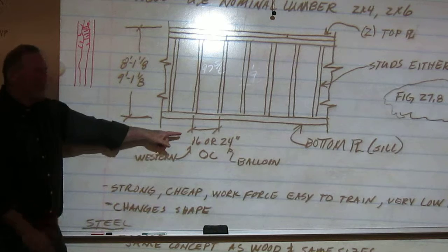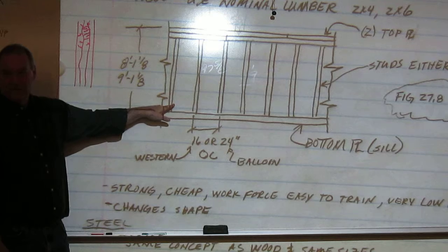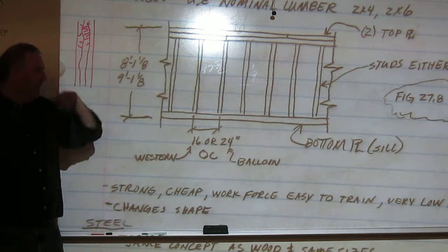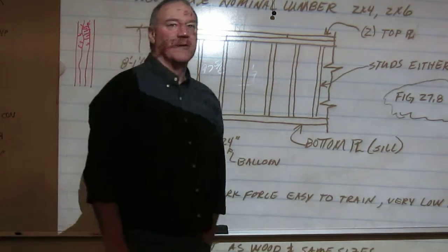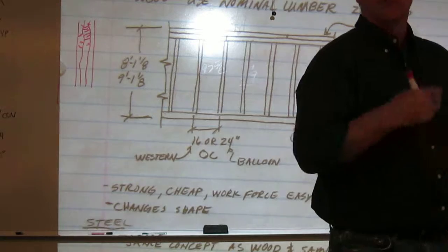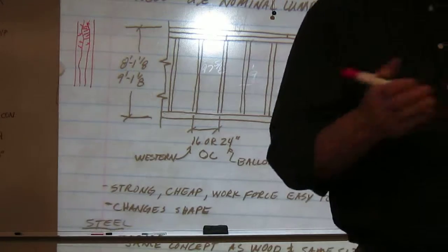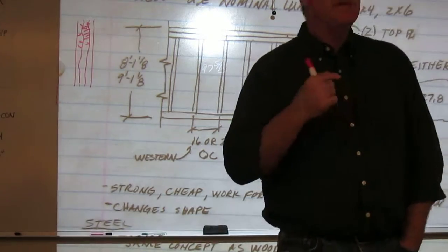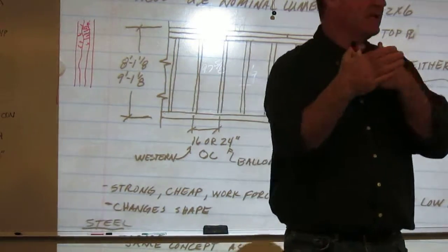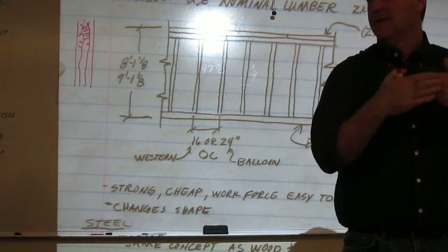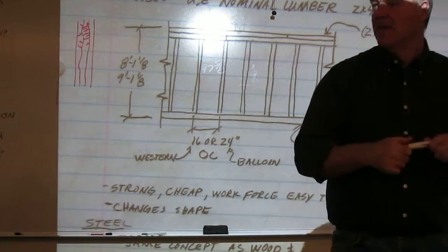For our area, we mostly use 16 or 24 inch spacing for walls. The 16 inch spacing is the preferred. And I really think this is driven more from performance than anything else. I don't have a real solid answer on why we use 16 over 24. It's actually a worse performing wall. I think people like it because when you go to the 24 inch spacing, your drywall has a tendency to vibrate and it sounds hollow. You can hear the reverb of it when you walk across the floor. It's also better for finding studs for pictures and hard things.